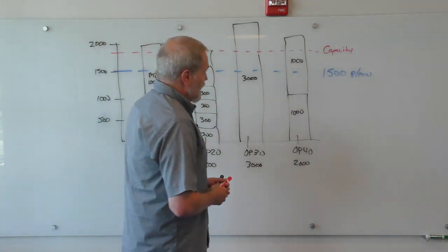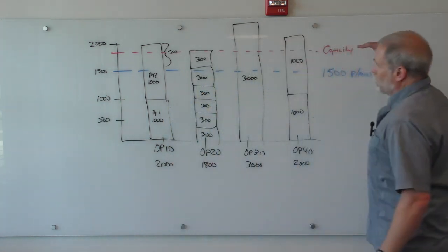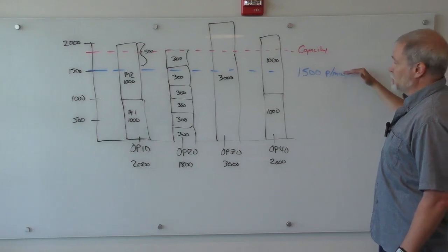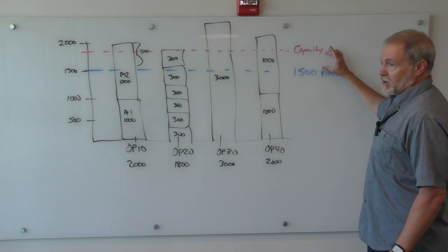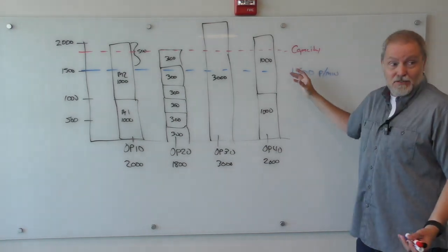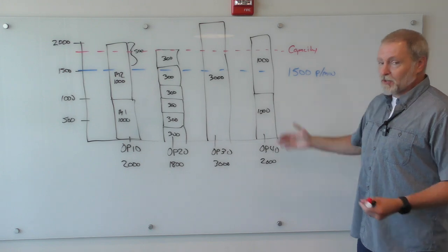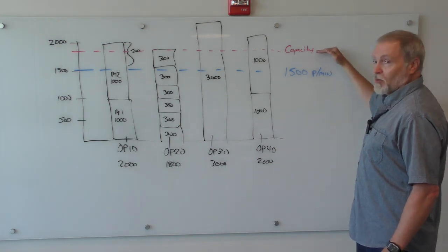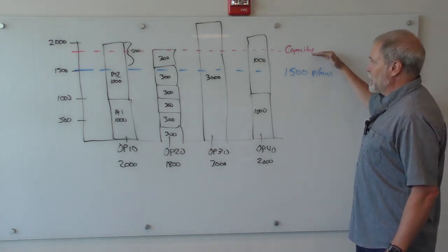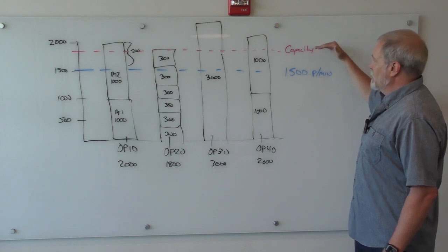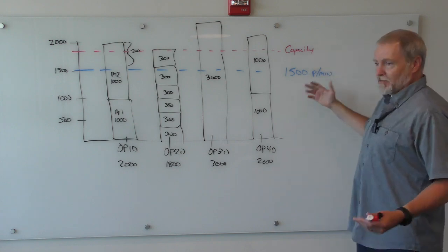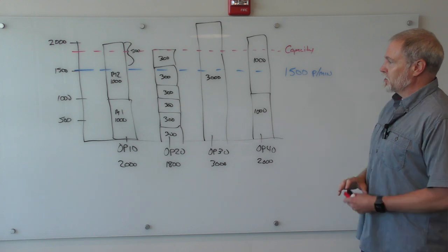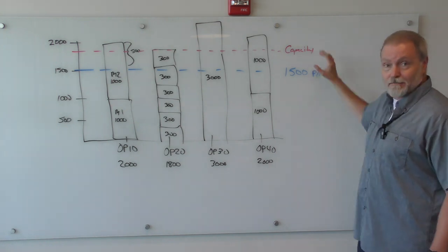So if we look at the difference between what our theoretical best capacity is versus what the target production rate was, that difference is our allowable OEE difference, right? If your OEE is less than 100%, which it is in almost all cases, you're not going to be producing at full capacity. You're going to be at somewhat less. And so typically you want to make sure that you've got enough capacity going in that if you're running at 80 or 90, whatever makes sense for you and your business, you still have the capacity to hit our target production goal. You want there to be some safety there.